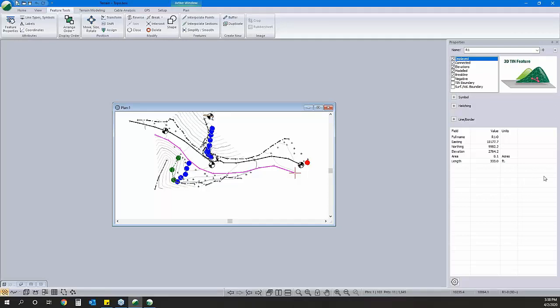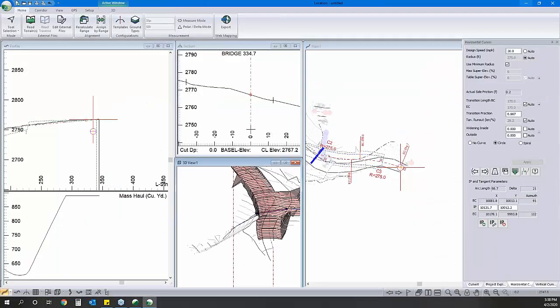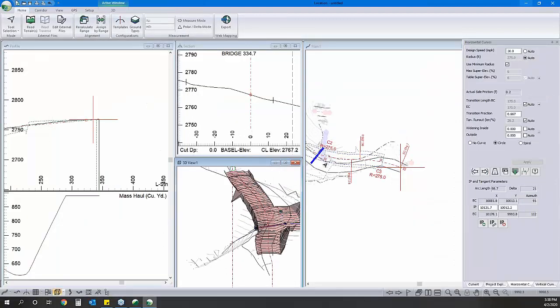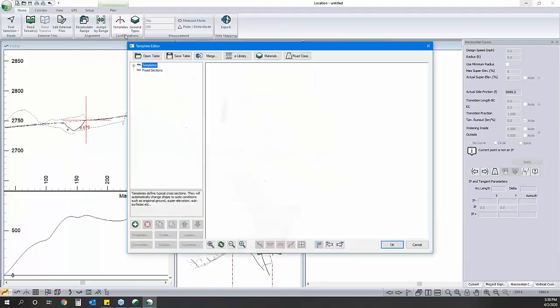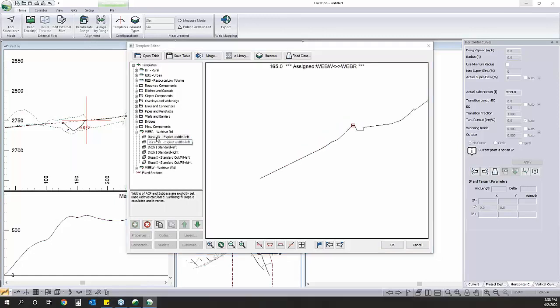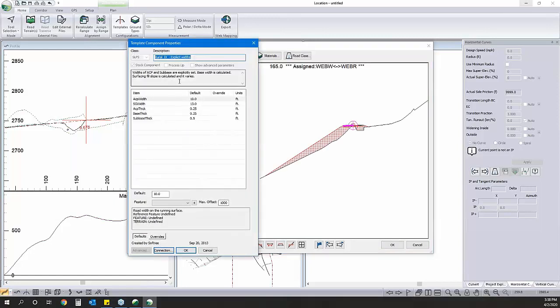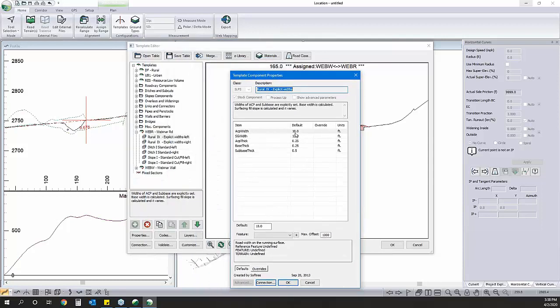And what I meant by ground level was under the template building section. So, yeah, in adjusting the different layer depths in the templates. So we come in here. Templates we're using have check marks next to them. So if we want to change something in our template, I just double click the parameter that I want to adjust, and we get the parameters option to edit.